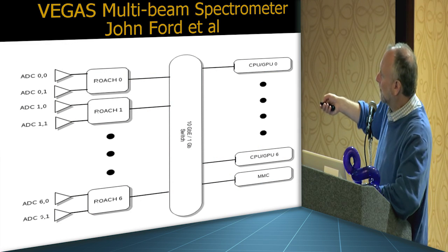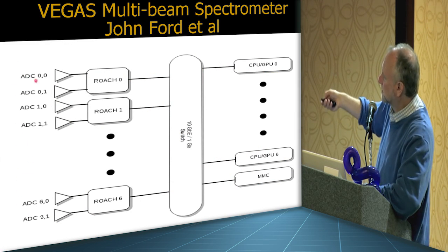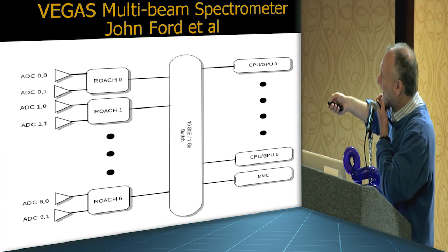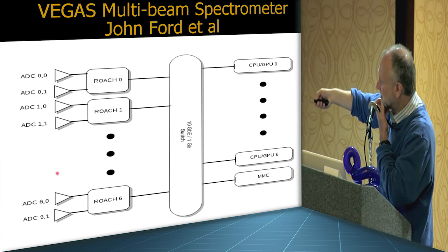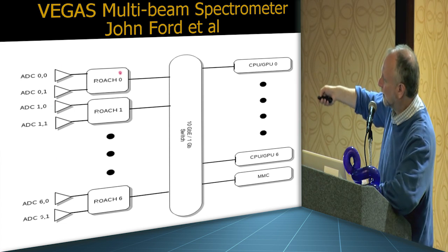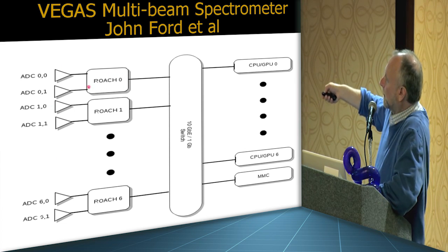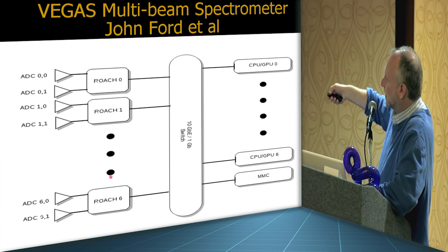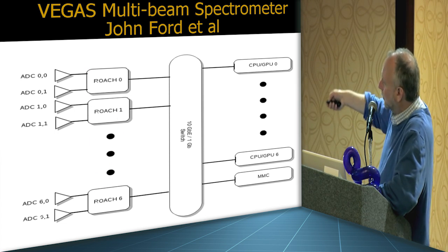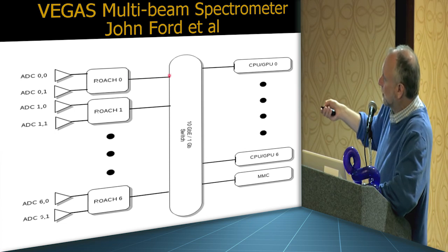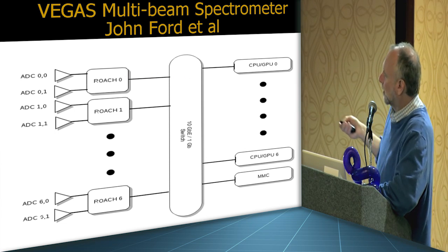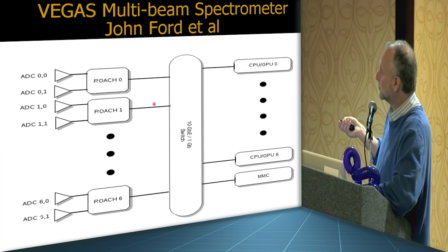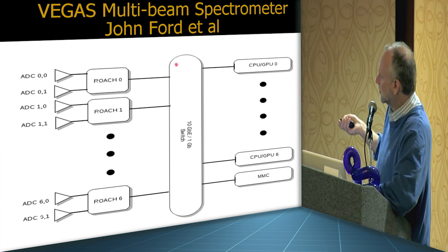So now we have a whole bunch of telescopes out here, or feed elements on a single telescope, and we're digitizing data from a bank of these things. And then these things are typically FPGA boards that are doing a little bit of processing to the data, but they're also in charge of getting out of this kind of synchronous world and going into the asynchronous times. So the packets coming out of here are time-stamped packets in either time domain or frequency domain data, or maybe both. And they're going into a big switch.